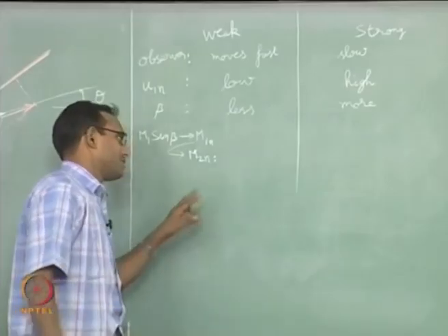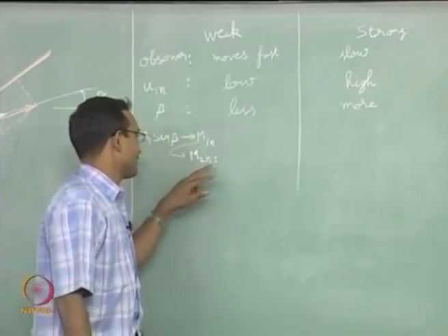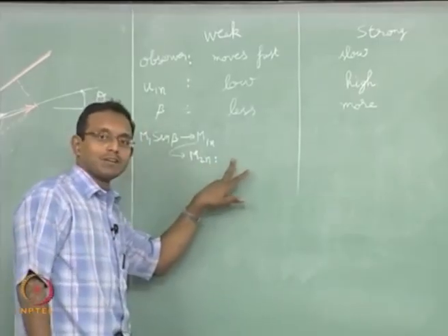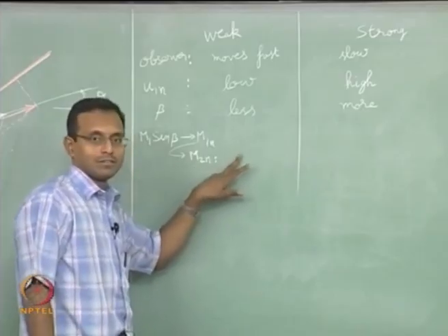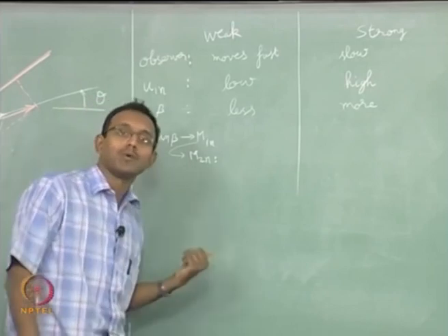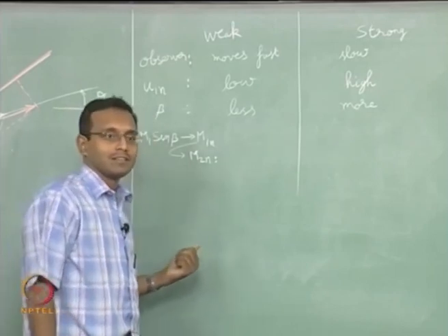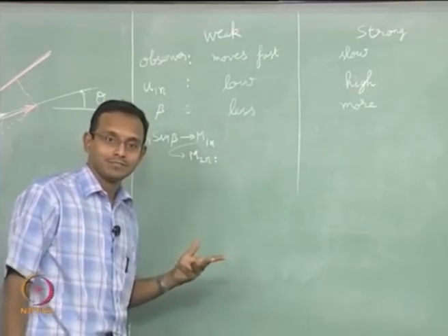This you have to remember from normal shock solutions: if my Mach number is low, the M2 normal will be closer to 1. We know it should be subsonic, but it will be high subsonic.